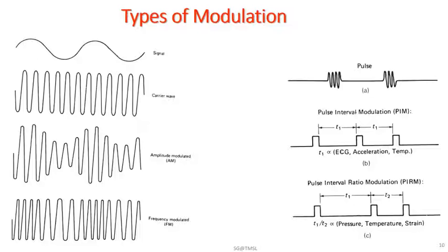So the biotelemetry system uses two modulators. The physiological signals are used to modulate a low frequency carrier, which is called the subcarrier, in the audio frequency range. The radio frequency carrier is then modulated by the subcarrier and transmitted. The double modulation gives better interference-free performance in transmission and enables the reception of low frequency biological signals.